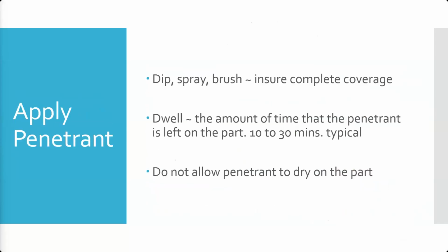Okay. When we apply the penetrant, if we're using a liquid bath, we can just dip the part in it. We can also spray it. If we're using an aerosol-based penetrant, we're going to spray it on. You can brush it on.